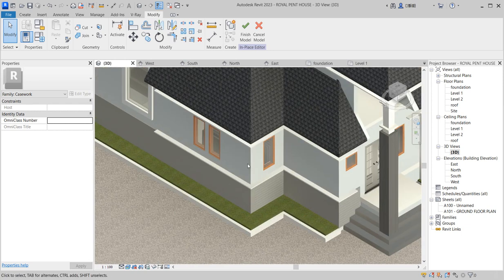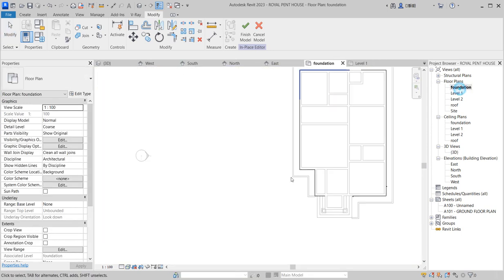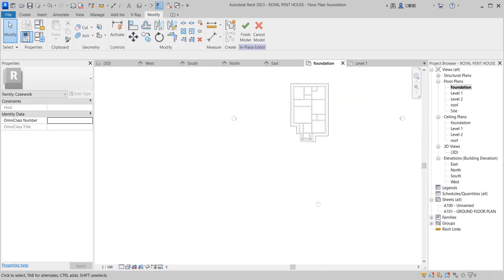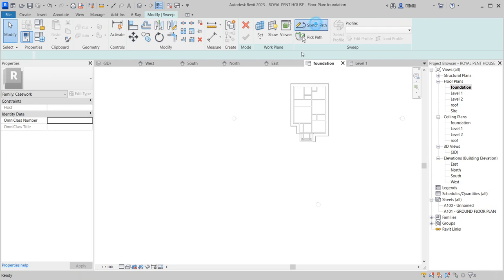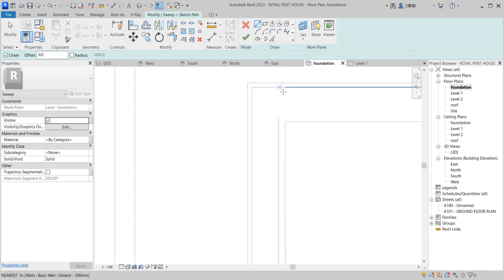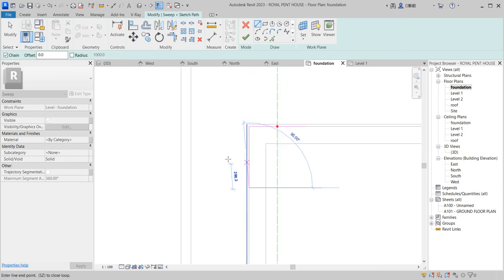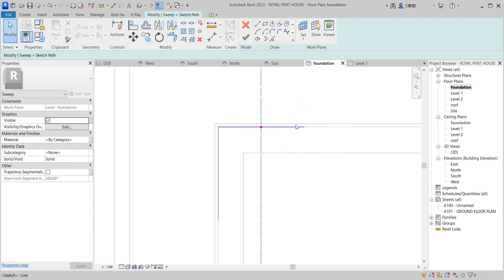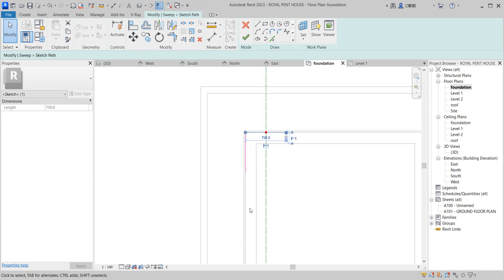So this is what you are creating that is giving an effective position. So the next thing I want to do is to work on these edges around. So I'm going to do that immediately. So click on this, click here like this, and you say, what are we doing? So create, use sweep if possible. So from the sweep, just click on it from here. So work effectively with the dimension so that we have everything accurately in position. So click here. So increase this one to 750. So you do the same thing here again. Increase it to 750.